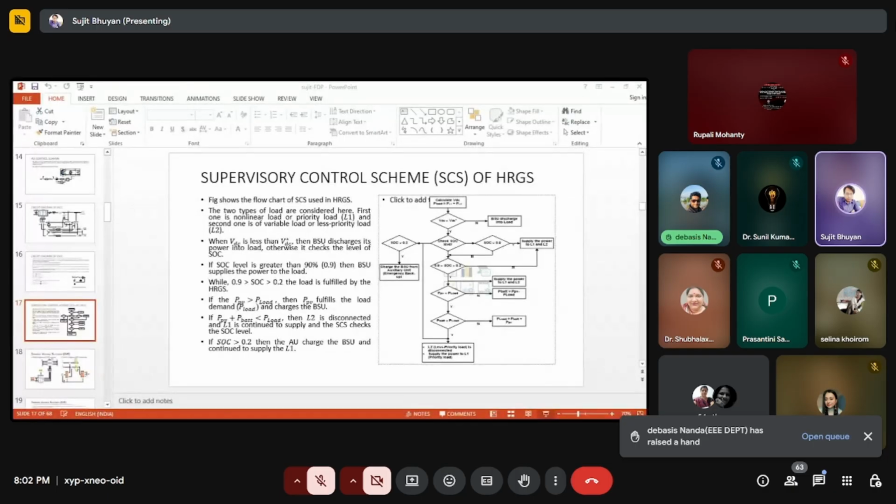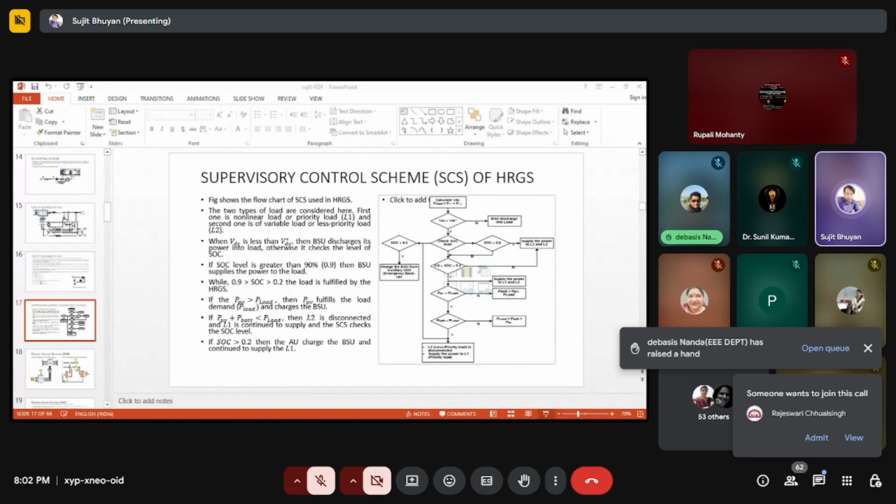Okay. And here, I think all of you know about the STATCOM circuits, right? FACTS devices, right? So there are a lot of STATCOM devices: DSTATCOM, UPQC, Unified Power Quality Conditioner, and so on. Here I have used the DVR as a simple circuit. It is a little bit bulky, you can say, but simpler than the STATCOM devices, UPQC, and DSTATCOM. So it is bulky, but less costly than the STATCOM devices.